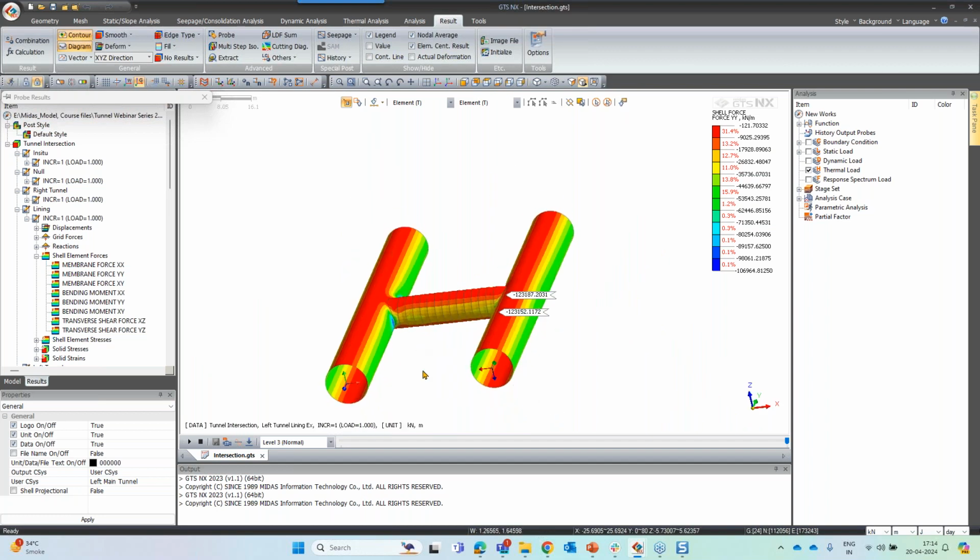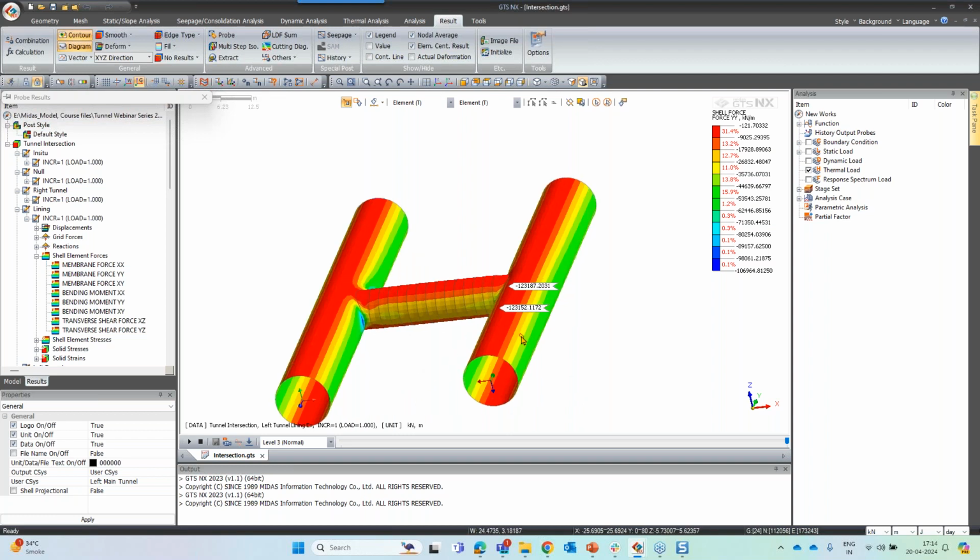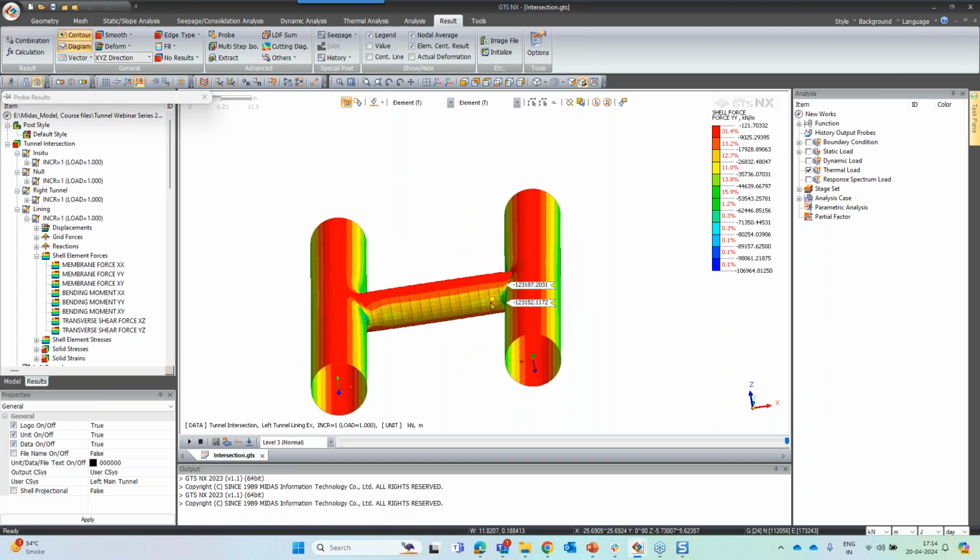And we need to plot our support capacity plots to understand whether this force is okay or not. Otherwise, we need to redesign our entire tunnel. That means instead of just 30% relaxation on the main tunnels, we need to go for more relaxation, maybe 50% or 70% on the main tunnel, and then maybe more percent of relaxation on the cross passages as well. Which will be a nightmare when you have a lot of huge relaxation in the field.